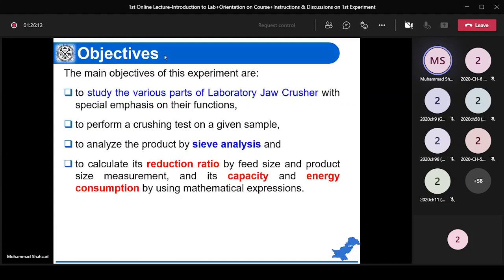If there are two fans having the same design, same wings, but one fan is consuming less energy, providing the same air velocity, then the fan which is consuming less energy will be more efficient. So simultaneously, we need to consider the size of the fan, the velocity it is providing, the pressure it is creating, and the energy it is consuming.